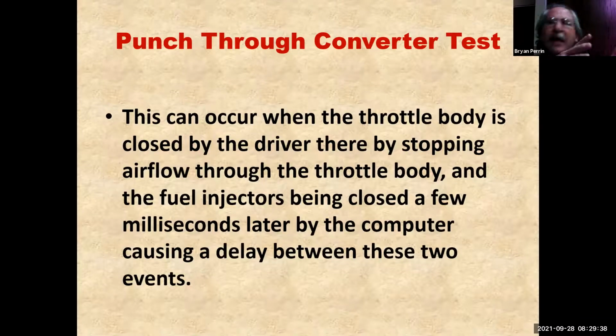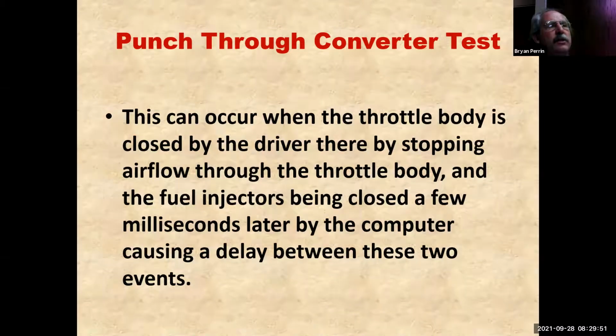So I can't do that test on those vehicles, but I really don't need to, because I can do an OSC test on those because all those cars have a front and rear O2 sensor. So I really don't need to do this test on that necessarily. This test is really designed for only fuel-injected vehicles, although there are some carbureted vehicles that'll work if they have a cutoff solenoid for decel. But I got it certified for fuel-injected vehicles without drive-by-wire.